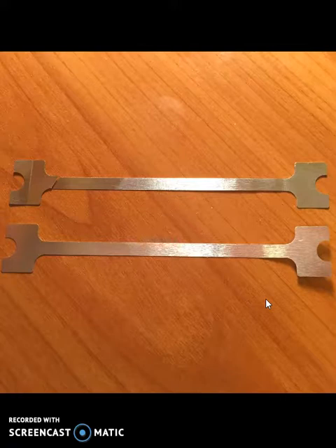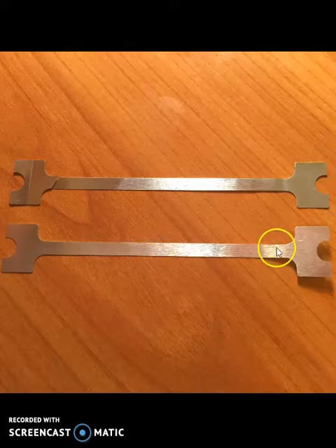We know that from the end of this fillet to the end of this fillet, the distance is measured to be about 80 millimeters. We also know that the sample coupon is about 4 millimeters wide and about 0.9 millimeters thick. So what I'm going to do first is go through a hand calculation to describe, if I clamp this thing down and impose 100 newtons of force, what the elongation would be.